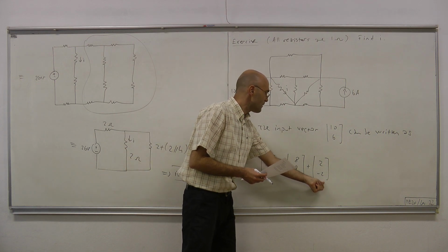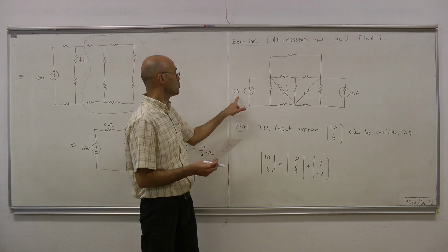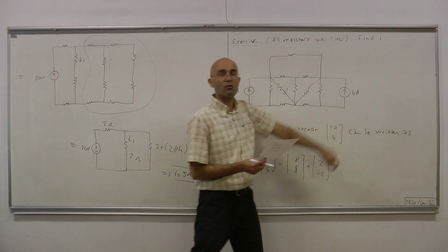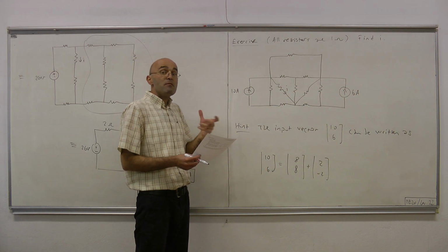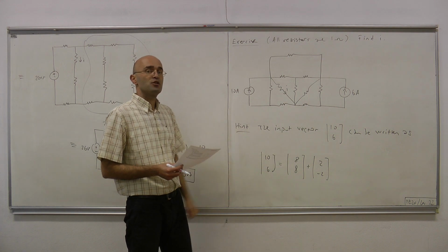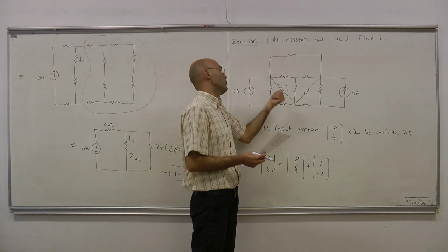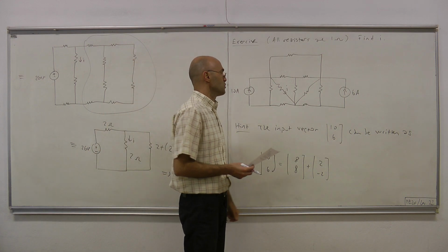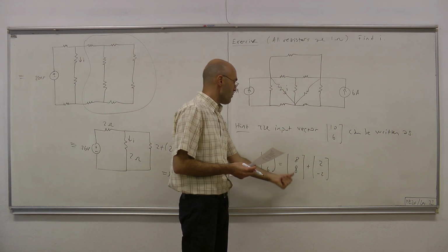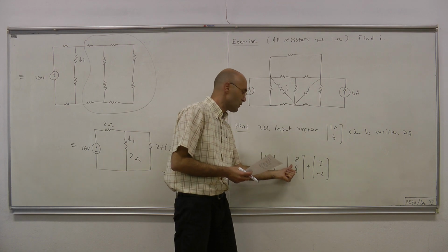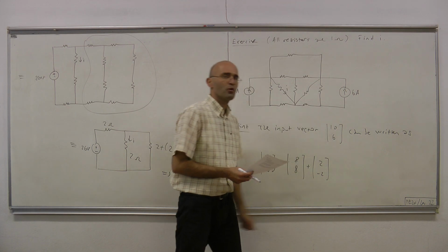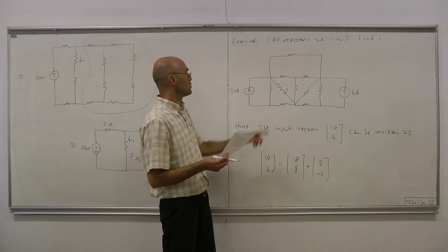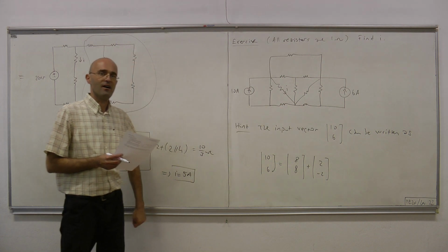And then we apply this input, that is 2 amps from here and 2 amps from over there. And then in that case, maybe we have a different type of symmetry, and that symmetry allows us to easily, perhaps, compute the component that we can call I2. And since the circuit is linear, we can combine those two components, I1 corresponding to this input, I2 corresponding to that input, and I1 plus I2 must give us the answer.